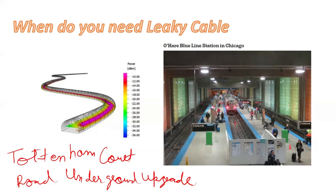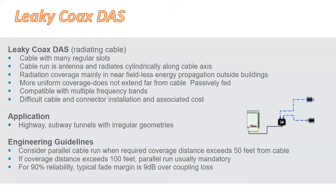A few years back, I worked on the O'Hare Blue Line station in Chicago as well. Here also, we have used leaky cables. Again, leaky cable is also known as radiating cable, and this is a cable with many regular slots distributed along the cable. The cable acts as the antenna and radiates cylindrically along the cable axis.